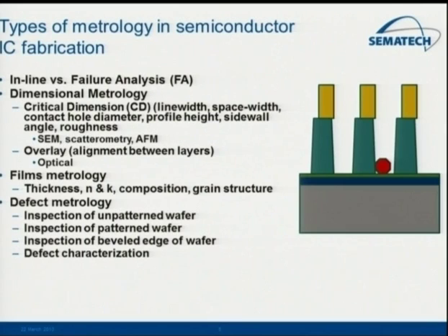Not just if it's a line, but also if it's a contact hole, measure how big that round contact hole is. Roughness of the films, I'll show some examples of that. If there's roughness along these lines, usually more in the top-down view, that could be very important.